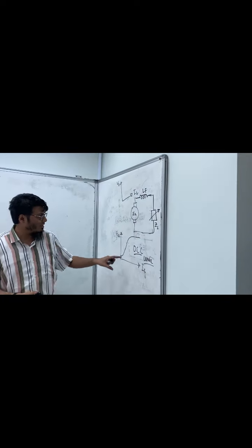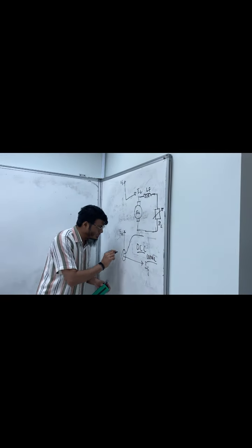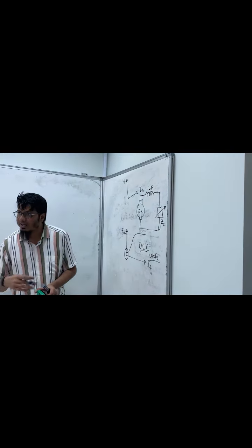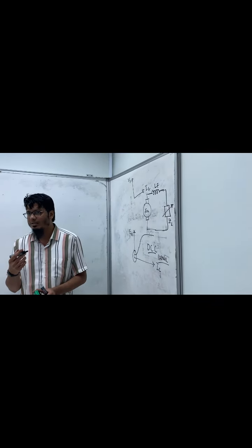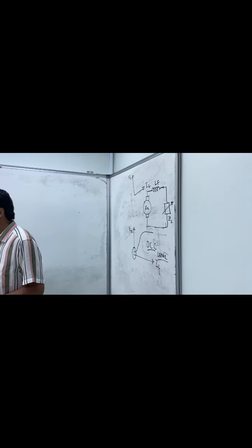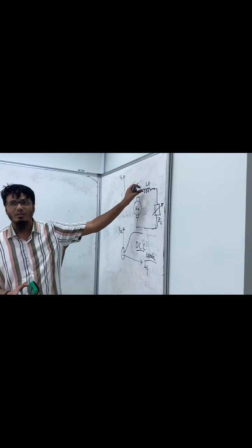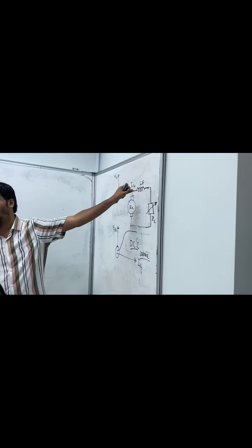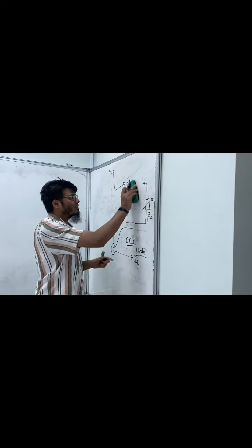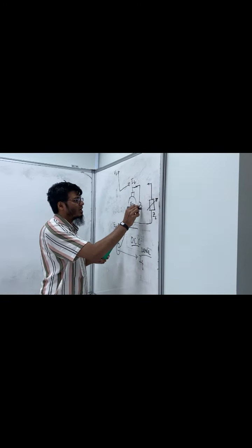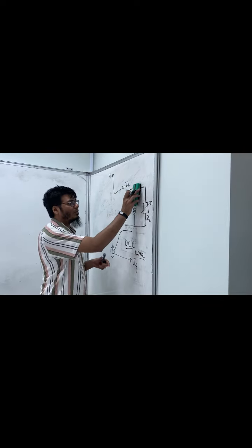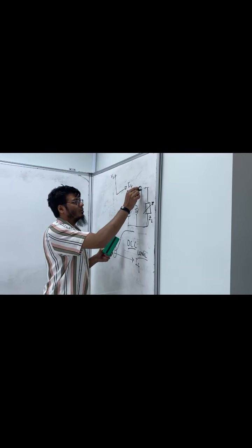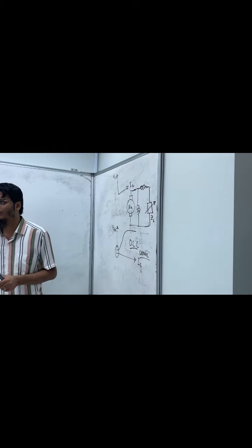And using the advantage of this residual magnetism, it will generate the output voltage automatically. You understand? So whenever we do the series, we will connect the field winding here in series. When it is shunt, we connect it in shunt. This is shunt. When this is compound, there will be one more here. This is compound.